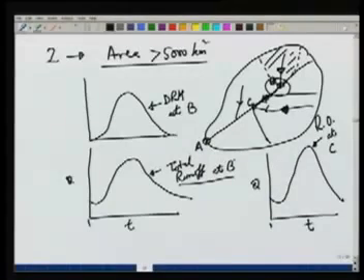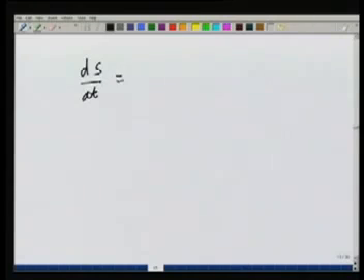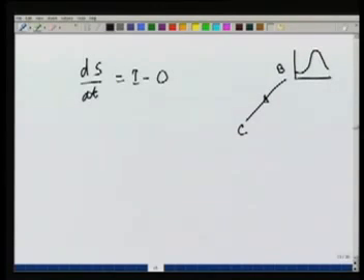Here, let's look at what we do once the flow reaches the point B, so we know what is the inflow at point B. The equation which we use now is same as what we have derived earlier, that net inflow should be equal to the rate of change of storage. So dS/dt equal to I minus O. So I'll draw only the stream here now. Point B, point C. At B, we know the inflow, because whatever the unit hydrograph theory gives us, we add the base flow and get the total runoff. And that runoff at point B becomes the inflow in the stream at point B.